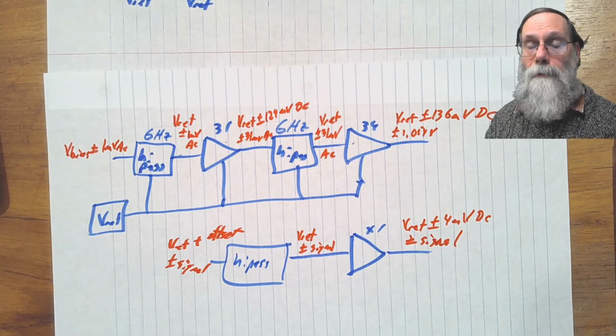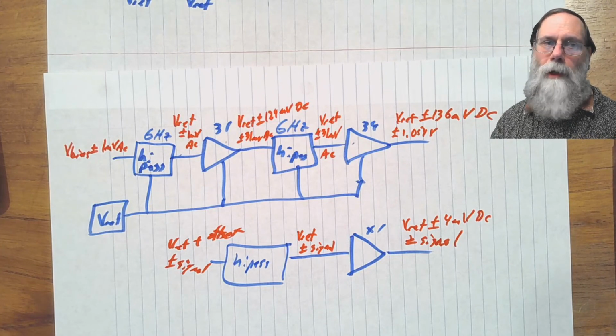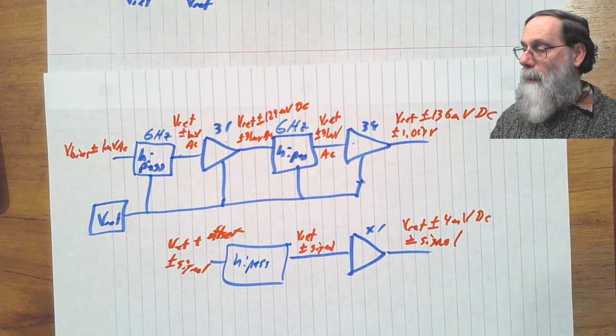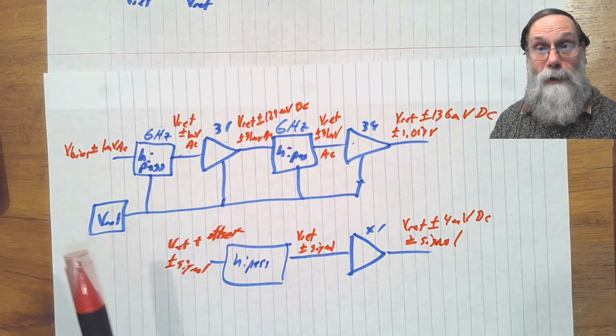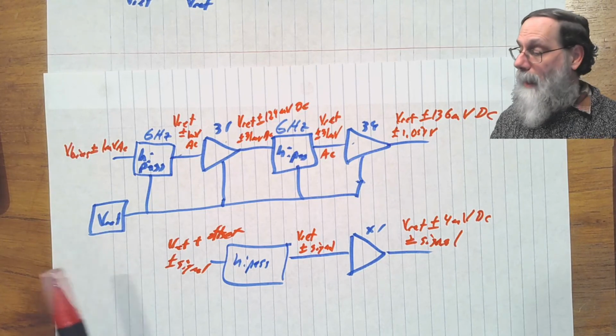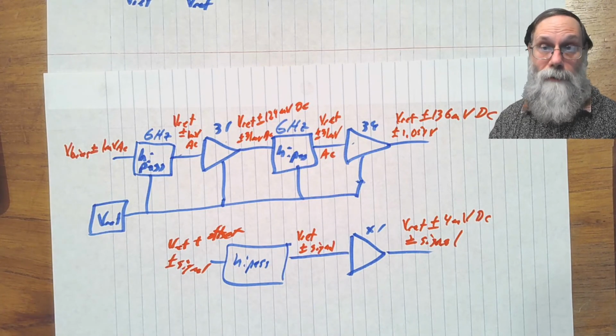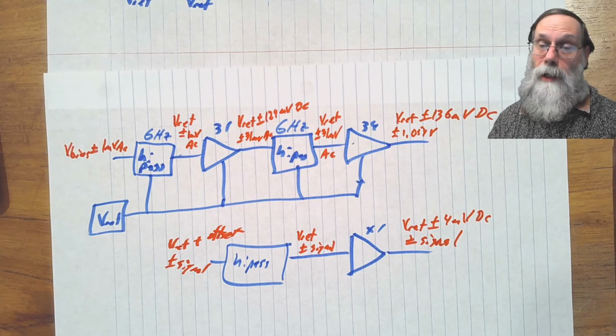So there's a lot of different reasons why we might want to use multi-stage amplifiers. The ones that come up most often in this course are the desire to have sufficient bandwidth while using an amplifier that doesn't have a very high gain bandwidth product, and compensating for the input offset when we want to get a large gain.